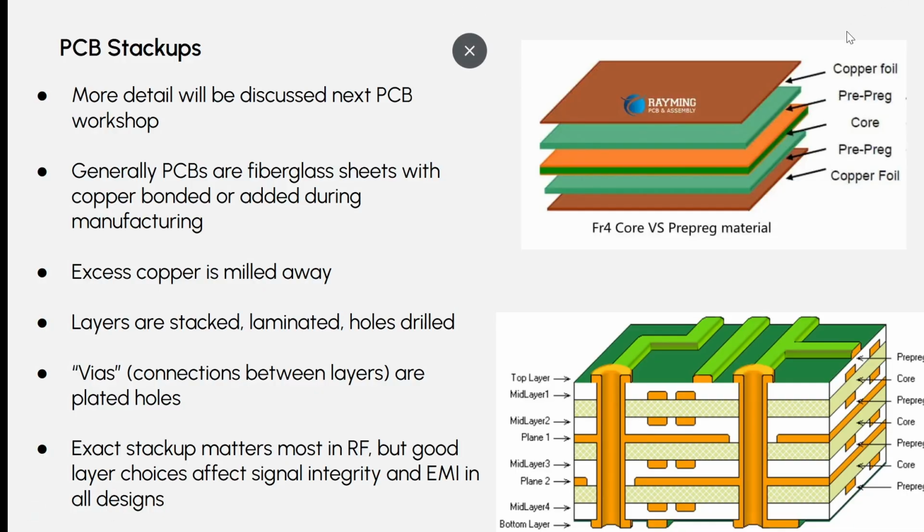Start with the copper on both sides, and then they just use basically a drill bit, obviously on a CNC machine, to mill away where you don't want copper. Now, if you want to make a 4-layer PCB, it gets more complicated because obviously you can't reach inside and mill it out. You have to start with separate pieces and then bond them together. And that's where prepreg comes in. So prepreg is used for those external layers.